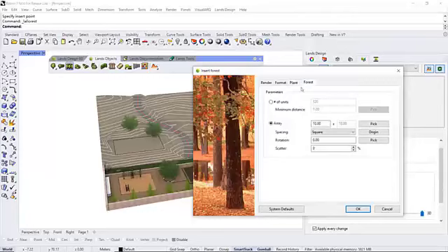And under the forest tab, I'm going to choose the way we want to arrange it. For example, we can select random distribution according to a total number of units, maybe insert a few less species, and we can also control the distance between each, in meters. Would be more convenient.